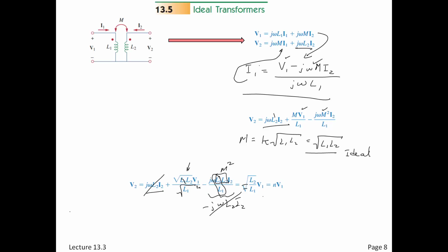And that is, oh, hey, there's the number of turns ratio showing up, which we like very much. So look at, in ideal cases, this is important. The two voltages, input and output, relate to the turns ratio. And so depending upon which way the ratio goes, as a fraction or a larger number, you can be stepping up or you can be stepping down. All right, and we like that idea.